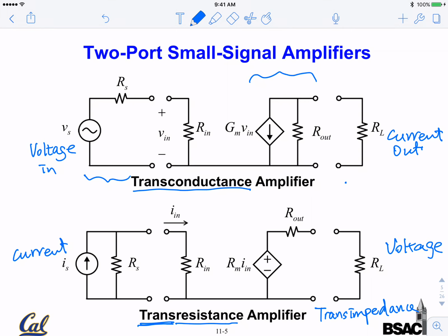The LED driver is usually the opposite. You will have maybe a voltage source. You really want to drive an LED, which is a diode. You primarily modulate the diode current. So this will be the case. You will need a transconductance amplifier for your LED driver. So you indeed have a need for all different varieties of amplifiers.